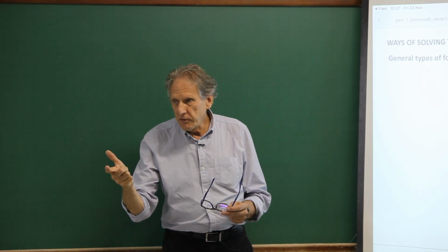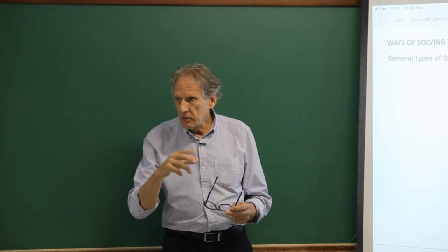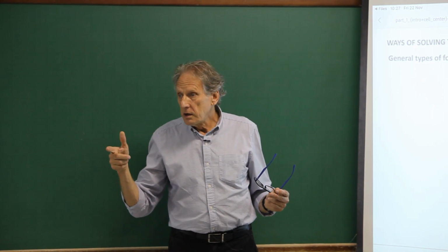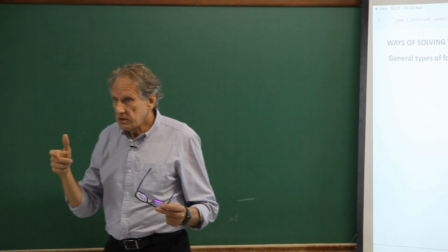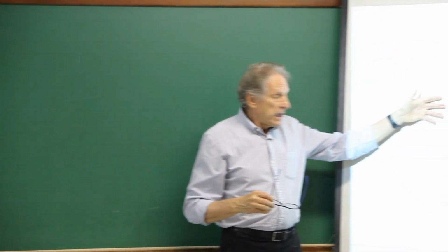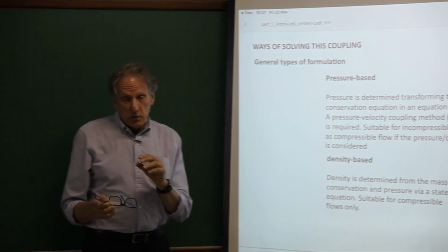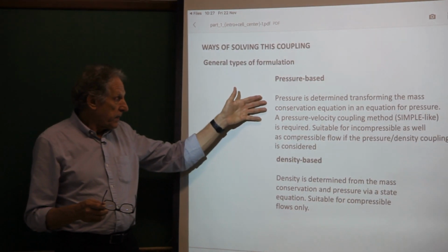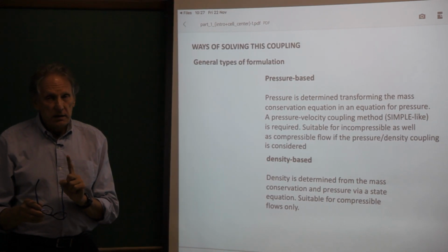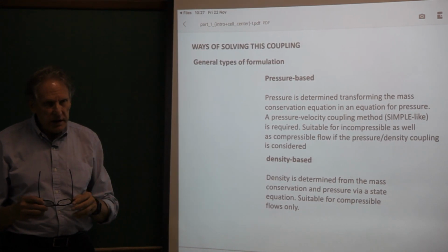Then this is suitable for compressible flows, right? Because if it's incompressible flow, there is no longer an equation of state to be used. So pressure-based is a method which can solve compressible as well as incompressible. This is also an important thing.